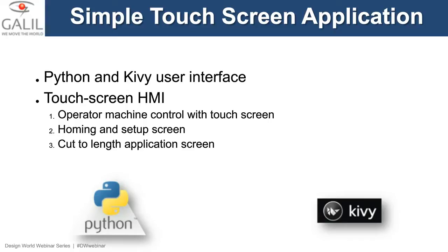It has a bunch of the widgets that you need: sliders, buttons, switches, text fields, all the little pieces that you need to put together a screen. And when you push a button, you can now call a piece of code that then responds to do something, update the screen, send commands to the motion controller, and really allow the operator to control the machine through this touch screen interface. So with these tools, the operator should be able to easily run this application. That's really the goal here.